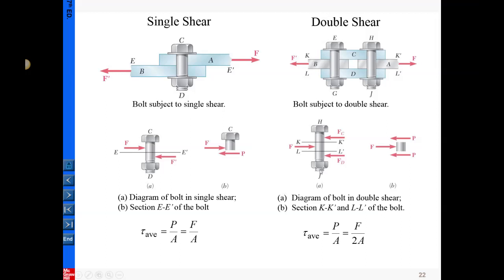Okay, we're back to the slides. So this is the double shear, and again, these are the pin's conditions. Under this situation, we take the free body diagram on the pin, and then in a similar way, we study the force being distributed on the pin. Again, this force applies through B. I think in this portion the free body diagram is this one. Okay, so that comes to here.